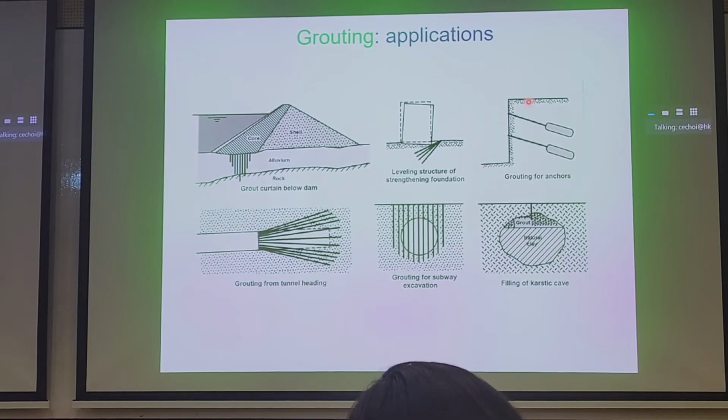So sometimes if you're looking at your FYP or your capstone project, if you don't want to put ELS in, you can put anchors in behind the wall as well. Maybe that will save you some trouble as you're excavating. So that's one option for you for your capstone project, ground anchors.